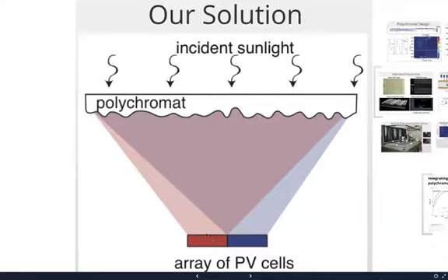The idea is that one solar cell has some material which can absorb these photons very efficiently because they're close to the band gap. And on the right-hand side, you have another solar cell that can absorb these photons very efficiently. Now you can see two things have happened. This optical element has separated the colors, but it has also concentrated the light onto the solar cell.